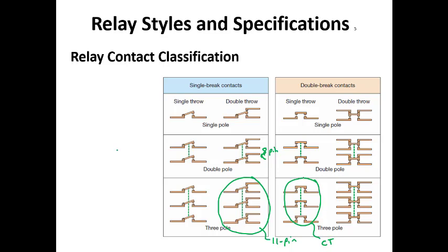So when we get to other classes, when we have our contactors, a lot of times they'll have 3 breaks, 3 poles. It's a single throw, 3-pole contact, and this is for 3-phase power. So you'd connect line 1, line 2, line 3 here. If you were trying to turn on an air conditioner, like an AC unit in your house, you would need a double pole single throw switch because if we have 240 volts, we end up with a line 1 and a line 2, both are hot, and so you need to break both of them. That's kind of the standard convention.